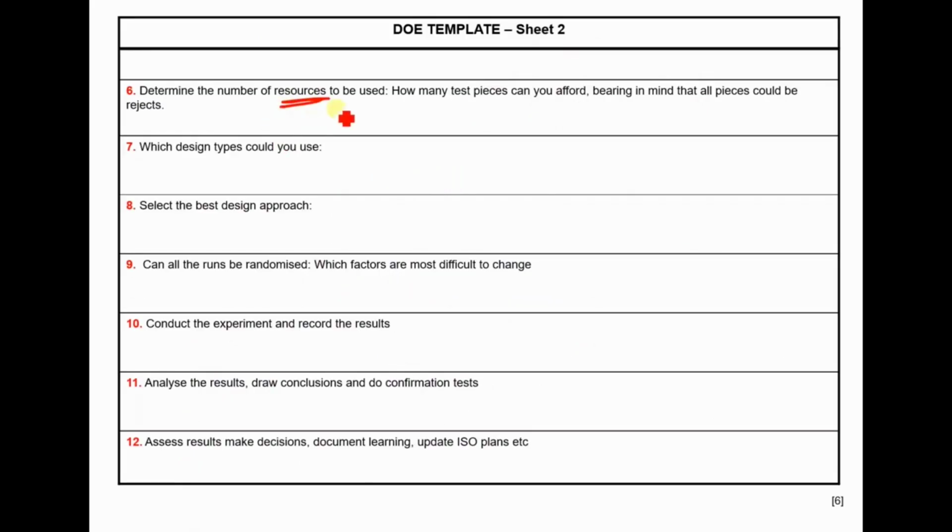Now we can go, okay, what's the sample size? Now the software, the technique itself, design of experiments, is looking for 30 to 50 samples. Okay, so you need to assume they will all be defects. You're going to push the process around to the edge of that design space. There's a good chance that's not where the good product sits, in those corners. Everything will be defective. So you have to take that on the chin. So sometimes this makes people panic with doing a designed experiment, but typically you're doing the experiment because something's costing you money. 30 defects at this point is normally cheap.